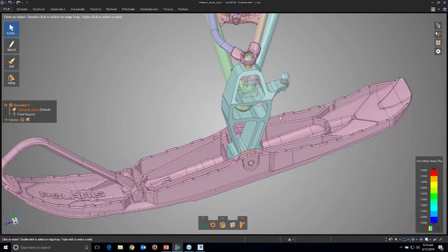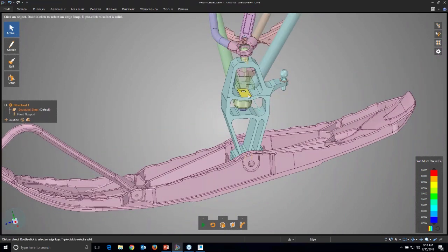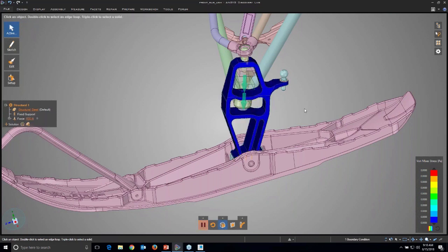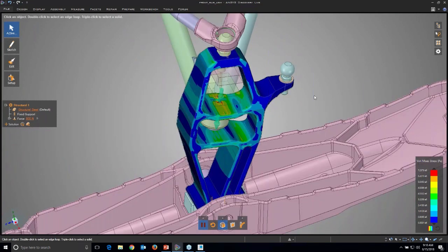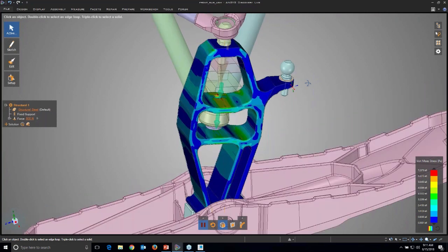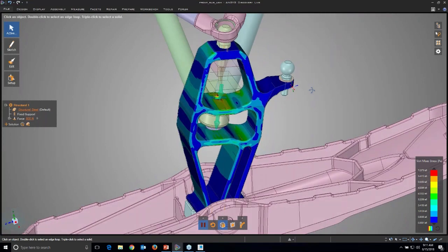And then we're going to put some kind of load in here, maybe these two surfaces, and I can put a force. You can put forces on here, displacements. I'll pick a force and just give it a value, and automatically, no meshing, nothing else, I get a simulation on the fly. Again, to do this kind of stuff outside of Discovery Live takes a lot more setup. Now in Discovery Live, it's super quick, accurate answers.